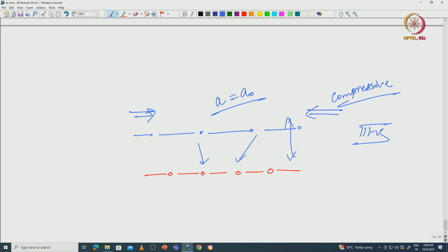So people do that by looking at a chart, a very famous chart. You can find it in any research group, or you can even find it on Google. On the y axis is basically the band gap of different materials. On the x axis is the lattice constant. Lattice constant is in angstrom. 1 angstrom is 0.1 nanometer. The band gap is in electron volt, eV, here.